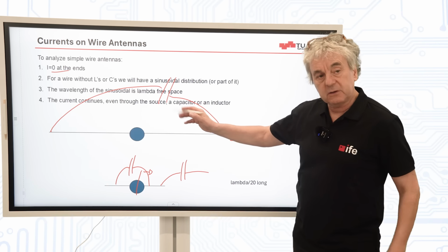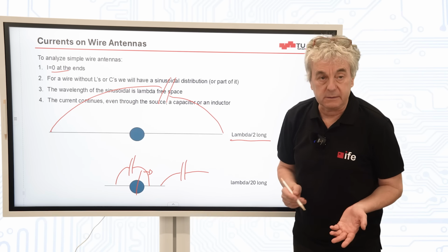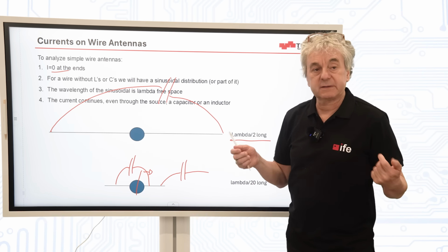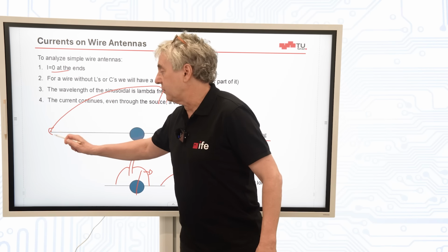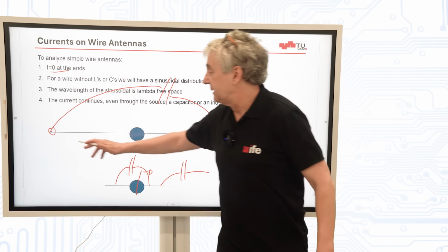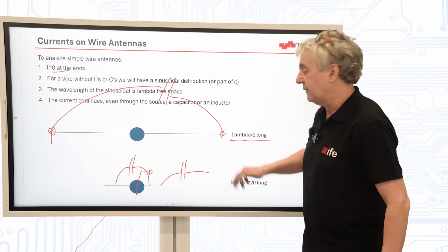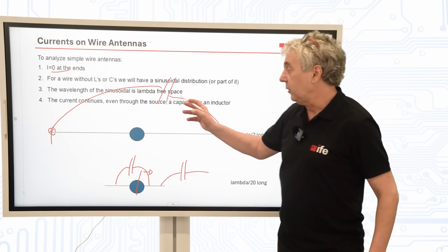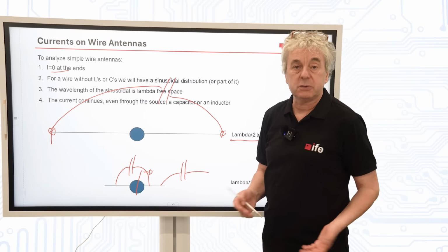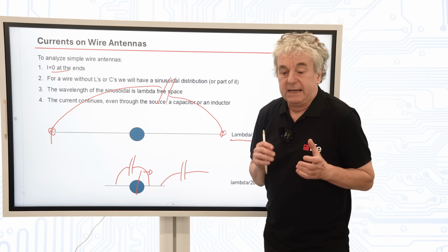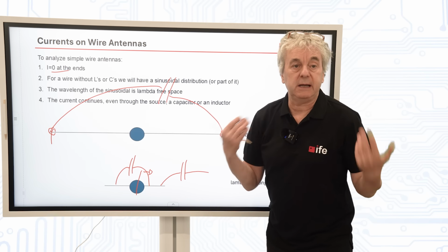We can only substitute the energy in the electric field by a capacitor if it's electrically small. Then action and reaction are directly bound between left and right. But the delay by the velocity of light is so high that thinking of this as a capacitor is wrong. That's a misapplication of the idea that we can express the energy stored in the electric field by a capacitor.